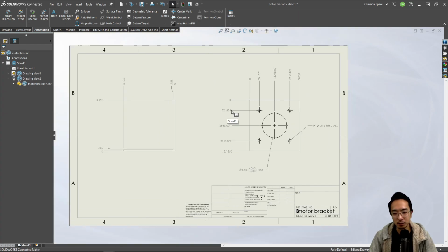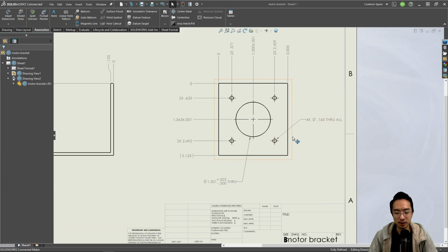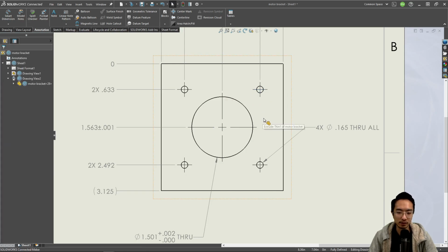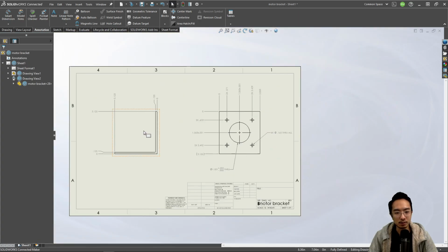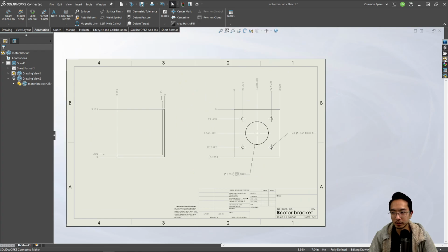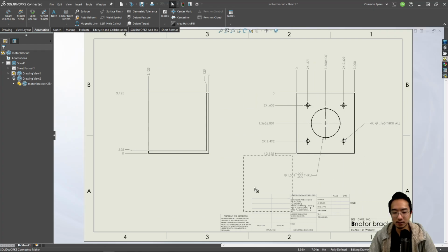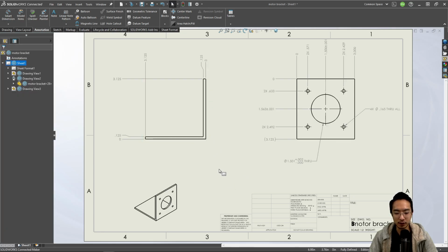Okay. Once you have dimensioned everything, we have the key dimensions, we have the key lines, we have all the holes specified, and you have these center marks for your hole. Sometimes, if the center mark size is not quite what you want, you could change the mark size to your wishing. But in this case, we'll leave it as is. So that's pretty much how you would make a part drawing. And then to put the cherry on top, sometimes you may want to add an isometric view somewhere in the bottom. This just summarizes what the final part is.